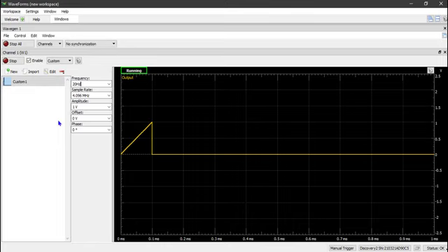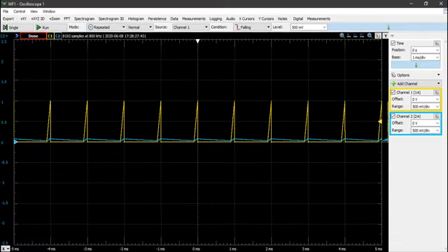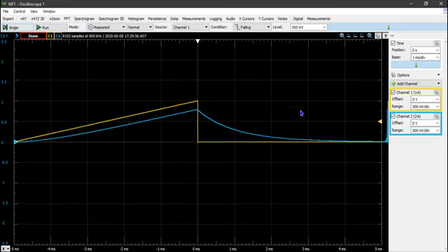Make sure it doesn't say 20 kilohertz. 20 Hertz. And since the formula for the function that we're trying to build is 200t times u(t) minus 0.005, at 0.005 seconds, 200 times 0.005 is 1. So we can leave the amplitude at 1 volt, and we'll get the correct waveform. Now let's head back over to our oscilloscope plot and press single, and you should get some output looking similar to this. This is exactly what's expected.